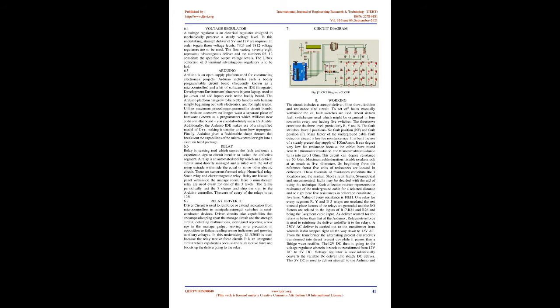Components. Power supply. The power supply circuit includes a step-down transformer that steps 230V down to 12V. In the circuit, 4 diodes are used to form a bridge rectifier, which provides pulsating DC voltage, which is then fed to a capacitor filter. The output voltage from the rectifier is fed to the filter to remove any AC components left even after rectification. The filtered DC voltage is given to a regulator to provide 12V steady DC voltage.